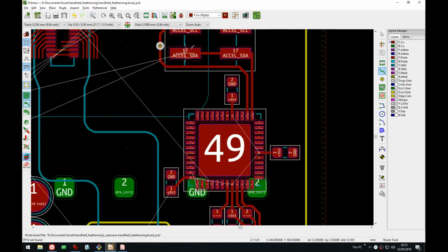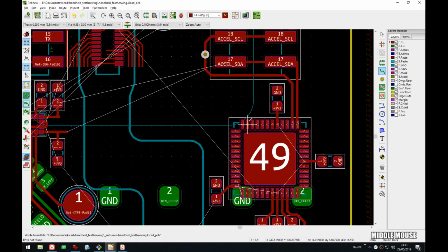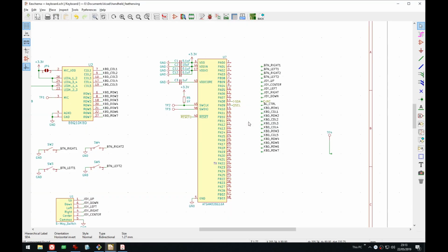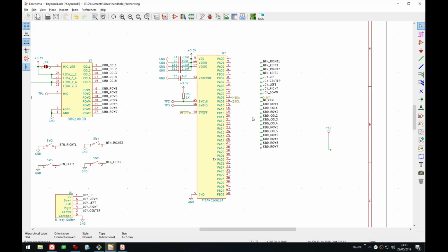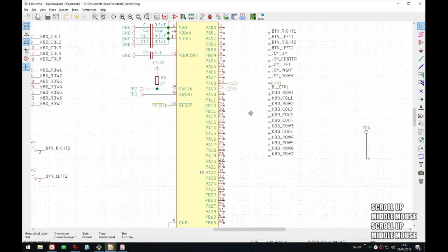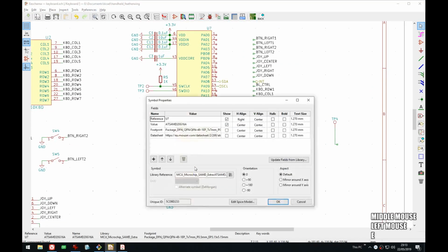So let's not move that for now. Okay, so I actually have to check where I can have the backlight control, because it's not everywhere. Oof, I'm so glad I remembered, because if I didn't check and it wasn't PWM capable, I would have had to re-spin it.